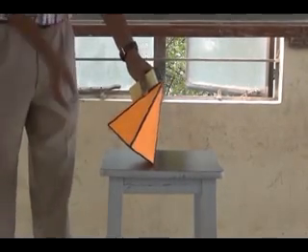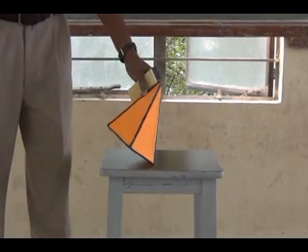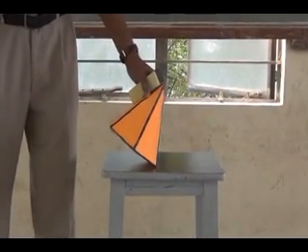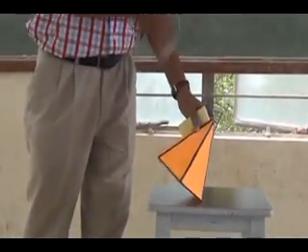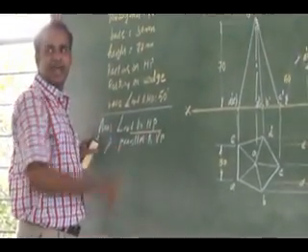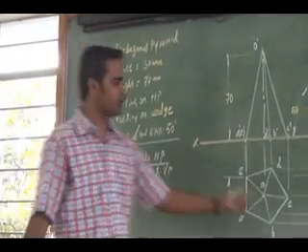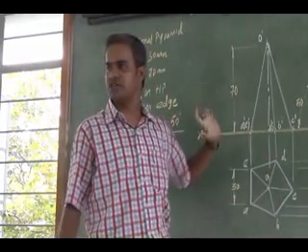Since the other corner of the base is tilted such that the corner is 25 mm above the ground, the base will be inclined. The axis also will be inclined to the HP. So this category also falls under the axis inclined to HP problem. Since the axis is inclined to HP, I can draw the pentagonal base on HP. Then I can proceed for the simple position.